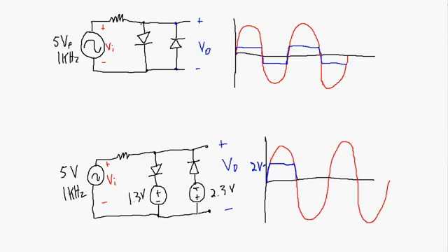So that point's 2 volts, even though it's probably not quite to scale, since this point up here is 5 volts. So at 2 volts, the diode becomes forward biased. No more voltage drop, because it's just going to take all the current through it.